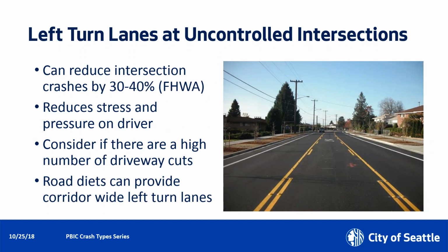And then getting into our uncontrolled intersection treatments, just left turn lanes in general. It sounds really simple and basic, but it's listed as one of the FHWA proven safety countermeasures that's shown to reduce crashes by 30 to 40% by just installing a left turn lane.